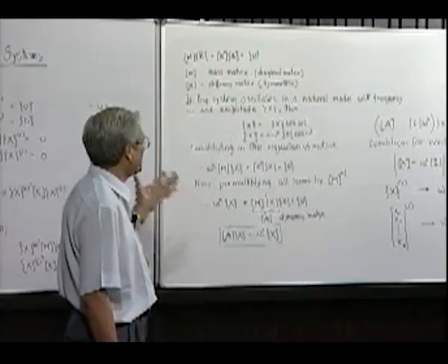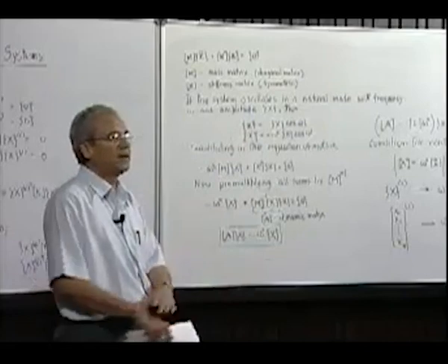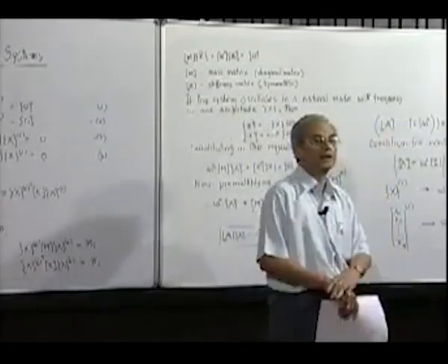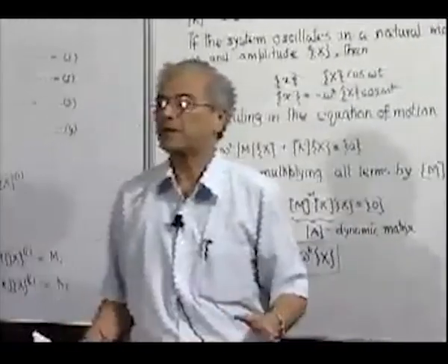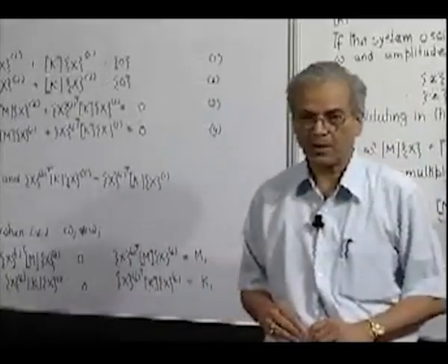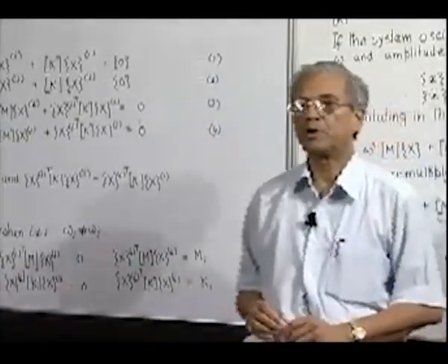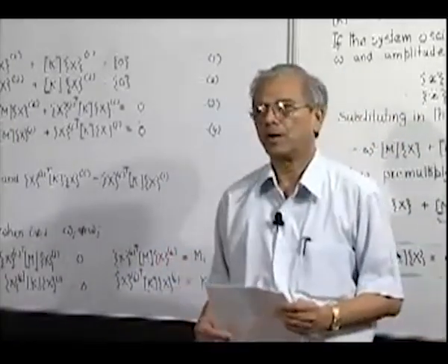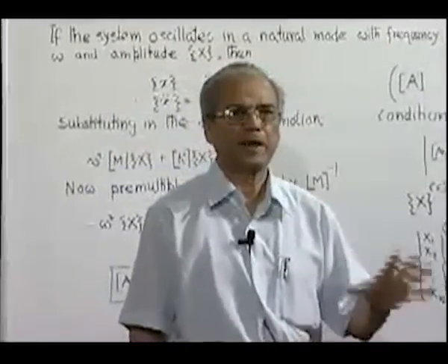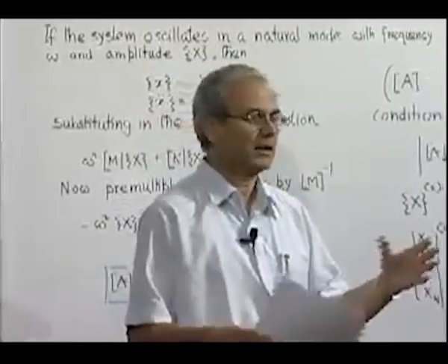The only thing is that it is computationally far less intensive than solving, for example, a 10 degree of freedom system, where directly solving a 10th degree polynomial is an extremely difficult task. So, we will next take up the methods of solving this multi-degree of freedom system. First, we will discuss the matrix iteration method, and subsequently we will discuss some approximate methods for obtaining very quick values, giving an idea about the order of magnitude of the fundamental natural frequency, that is the lowest natural frequency.